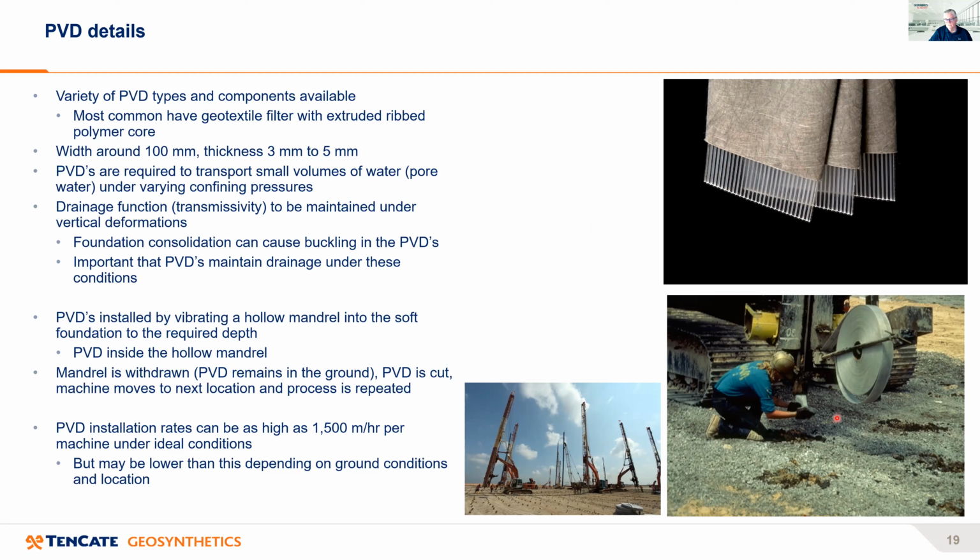Now, the wick drains are actually installed inside a hollow steel mandrel, such as shown here in the bottom right photograph. You can see the wick drain coming out at the bottom. These mandrels are vibrated into the soft foundation layer to the base, and then the mandrels are withdrawn back out to the surface, and the wick drain remains in place in the soft clay foundation layer.